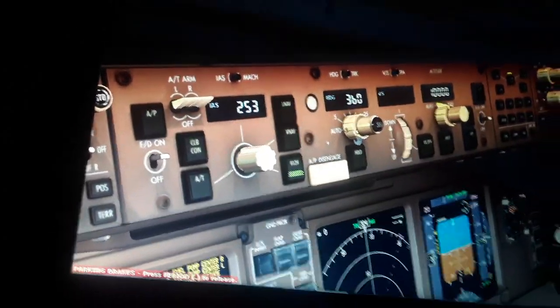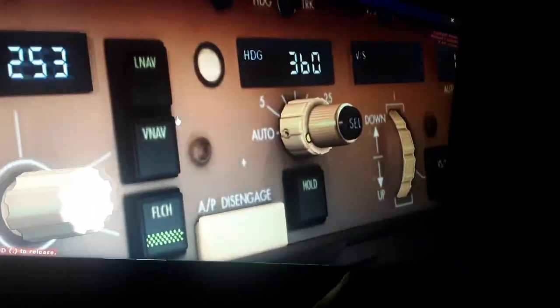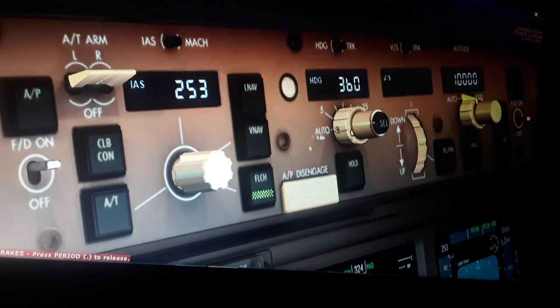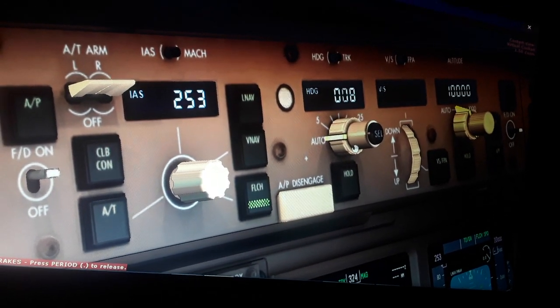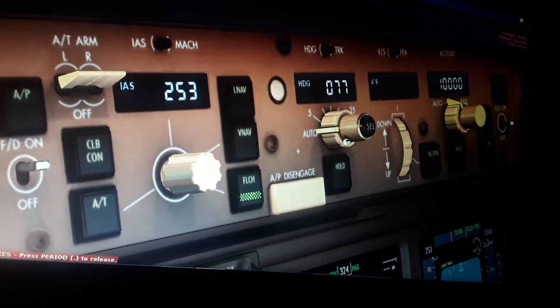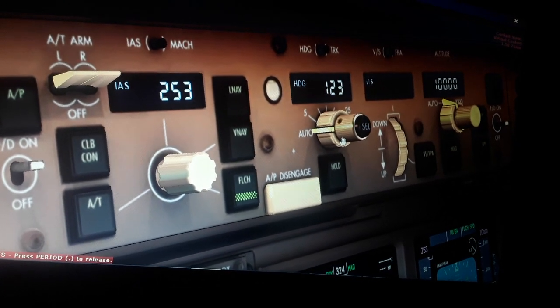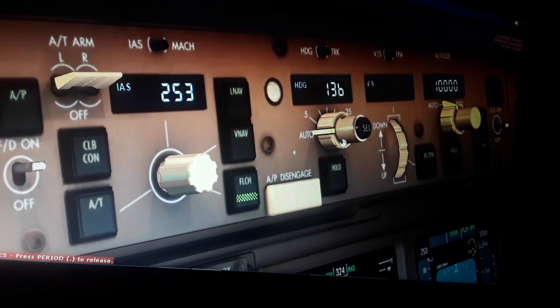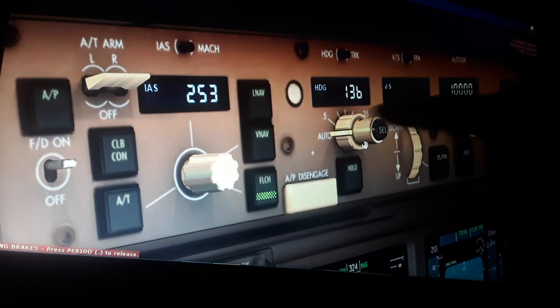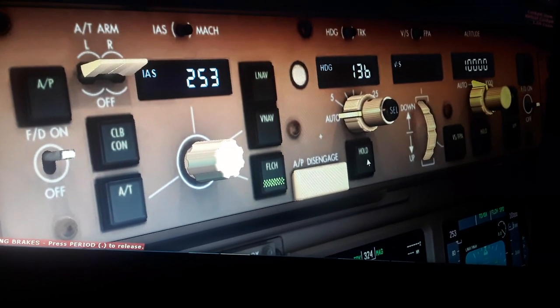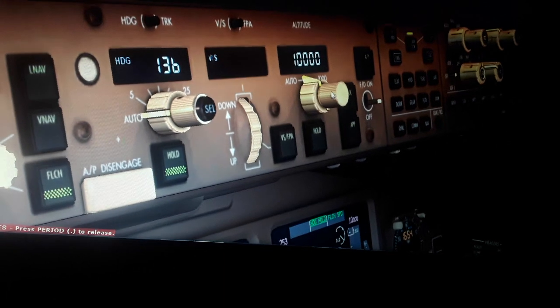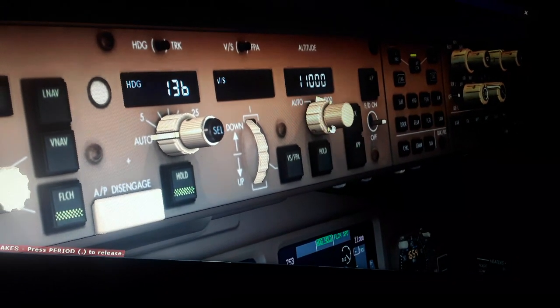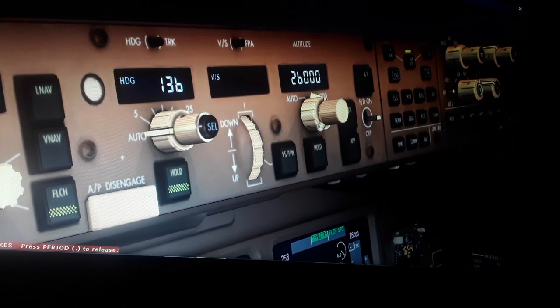After takeoff we have the bank angle limit over here, the 360 degrees the heading, so it's different. The bank angle is for the autopilot to follow, while the heading is the desired heading we need to follow. The bank angle limit is how steep the aircraft banks in the air. We can hold some mode also. We have the vertical rate. I will set the target altitude also here.